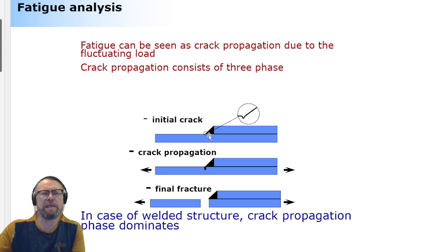The welded joint is this particular region, the area color coded by black here, representing the weld. This is one steel plate, and here's another steel plate, and this is where they're connected. Now, the weld toe, this particular detail, when you take a close look at what happens here, you can see that there are initial cracks. That's simply because of the welding process.